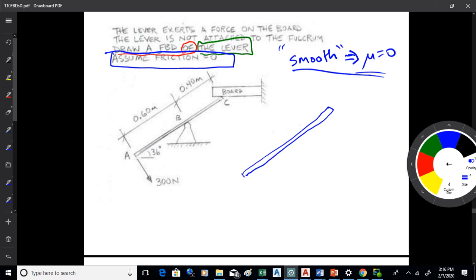Okay, now just pay attention to the direction of your forces. What's the rule on smooth contacts like that? The force is what? There's a little wording we used on that. Normal, yeah, to the flat surface, right? So the forces are normal to the flat surface is the way that's expressed. Okay, that's the key on being able to draw the forces going the proper direction.